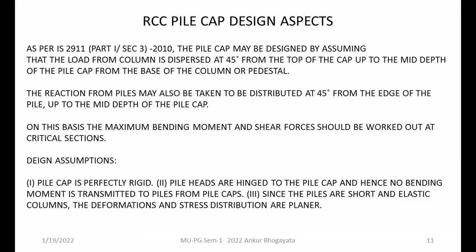Right now we are focusing on pile caps itself. Since the piles are short and elastic columns, the deformation and stress distribution are planar. This is also an assumption, right? But in actual practice, when you take the slenderness ratio, it may happen that the piles are no more short members. They don't act as short members, so they act as slender members.